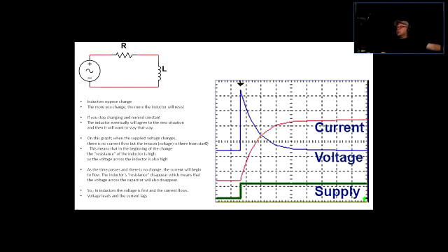So of course, as opposed to the capacitor, at the starting point, this moment right here, the voltage of the source, the power supply, goes from 0 to high, whatever that level is. Then the current is going to be pretty much 0 because coils hate change.